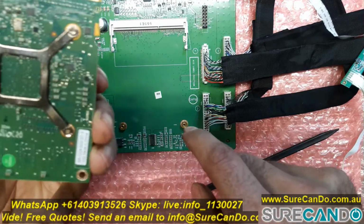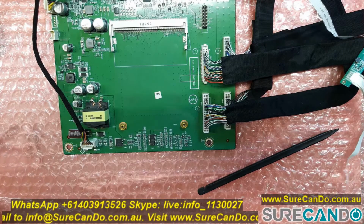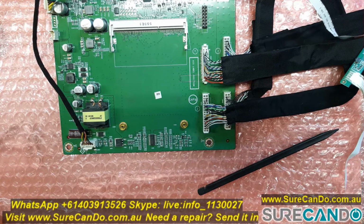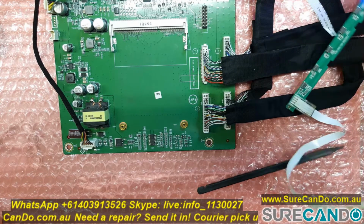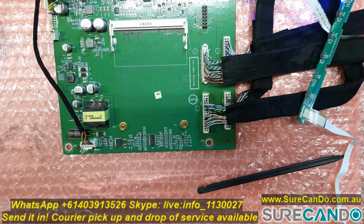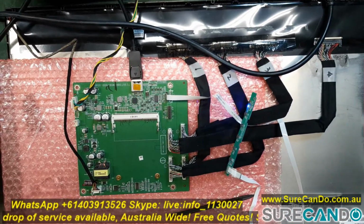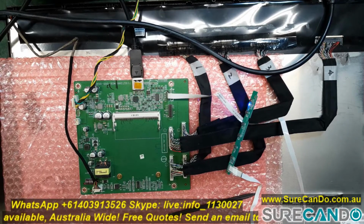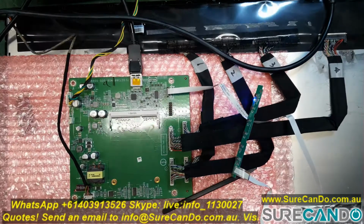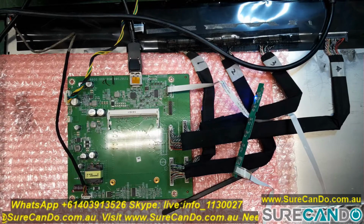Then I decided to see what would happen if I turned the monitor on without the G-Sync module, just as is. So let's give that a go. Alright, here we go. I've turned it on, and when I check the LCD, there's not even the Acer logo coming up with the G-Sync on the bottom right corner. So this told me that the G-Sync module was working properly, so we can ignore that and assume our G-Sync controller is okay.